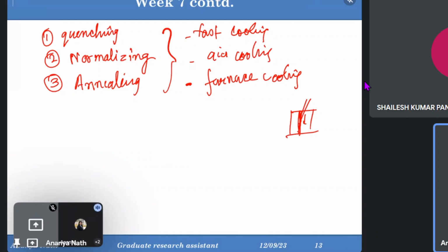Solidified means there will be solidified grains. Before that, there were lattice structures, but in the melted state, the distance between lattices is larger. Now you are suddenly freezing it. Suddenly freezing means the lattices will not care how they are arranged. They will just solidify because they don't have any other option. The temperature is not high enough for them to sustain the liquid state.